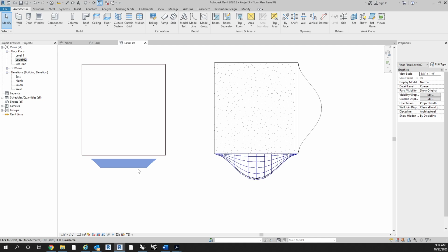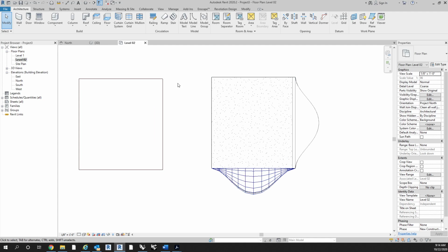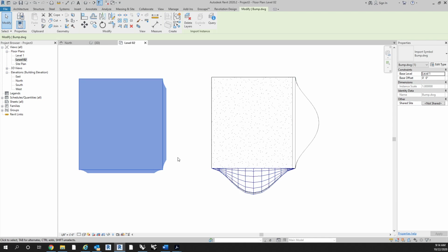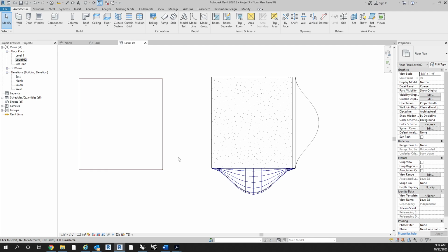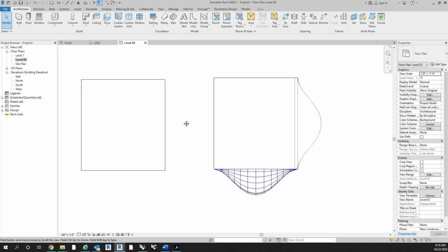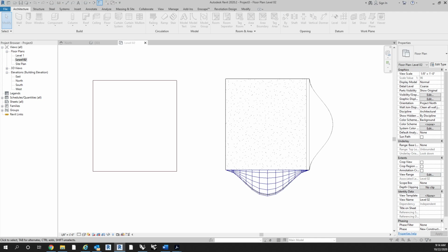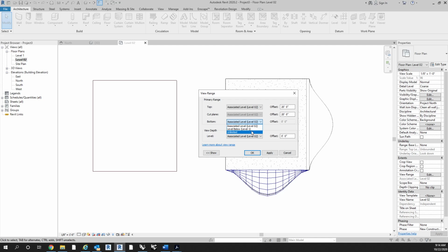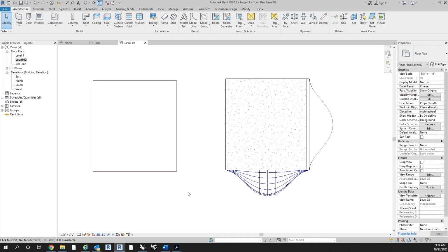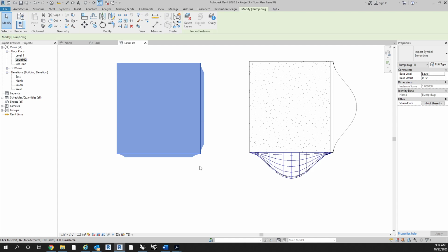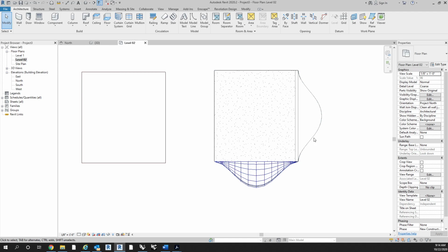One is that it doesn't appear like this is being cut through. And one thing with imported files, I don't know if it's because it was originally designed to only import two-dimensional files, but when you're linking or importing CAD geometry directly into a project, let's just make sure the view range is turned on. Yeah, so even still, it doesn't cut through the geometry like it does here, right? If we were on level 2 and we're cutting through this geometry, it should have the curvature highlighted.